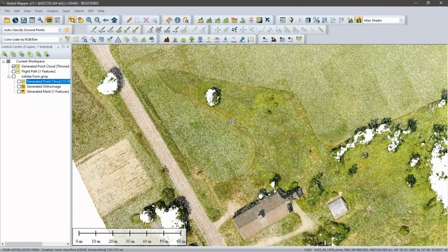Just going back to some of the questions, I will in a second, Mackenzie. One of the other questions that came in earlier was about ground control, and if you want to apply some sort of rectification as a post-process, there are a couple of ways of doing that. I mentioned the LiDAR QC. This will allow us to go out after the fact, identify recognizable features in this area, derive the three-dimensional coordinates of those recognizable features, and then import those points. And within the local context of those points, it will adjust the vertical position of those points. It's a vertical offset, and it interpolates between those points. So that's a post-process you can apply to improve your vertical accuracy.